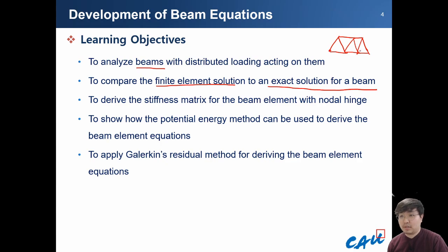So I think you can obtain some solution. This bridge maybe consists of truss elements. However, when you replace them with beam elements, those results are slightly different when you consider the deflection of the beam structure. So I think the next homework is the comparison between the truss and beam structure.